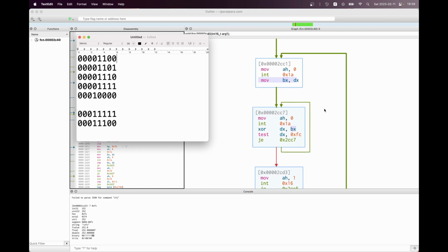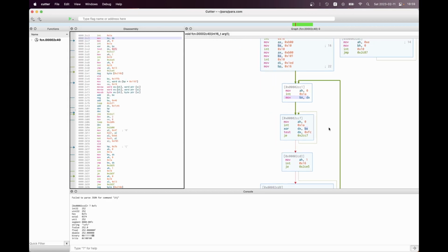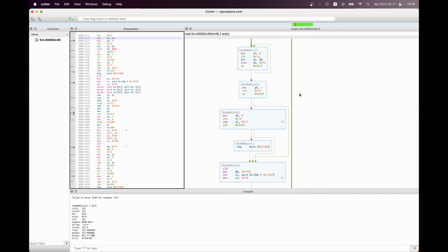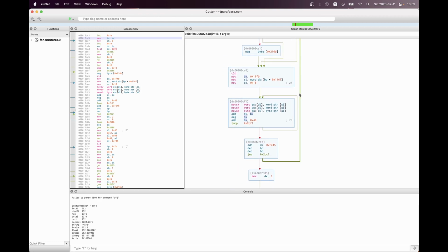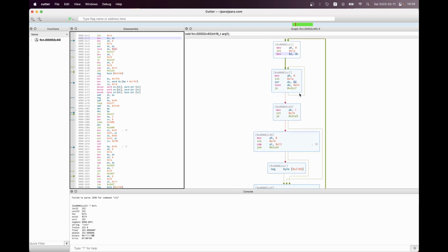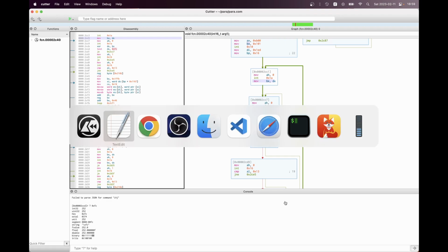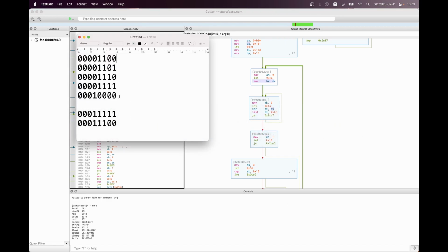But keep in mind that we are inside a loop here, and that what follows that little wait routine we're currently looking at is pretty simple. So there's a pretty good chance that we will get back to that waiting routine in so little time that the timer will not change in between. Which means that once we triggered the break from the loop, the last 2 bits are 0, and they will still be 0 when I come back into that loop.